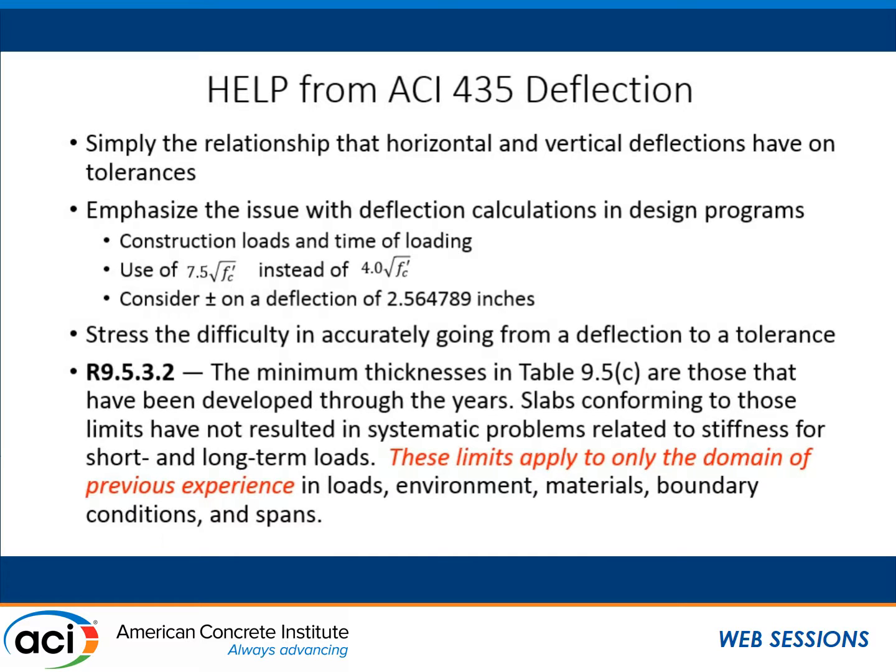We discuss it in the American Society of Concrete Contractors. We've got a little bit of an issue because most owners will pay for F-number measurement, okay, FF and FL. The testing lab does it. It's already in the testing scope, so they pay for that. The difficulty we have, and I used to own a test lab, is you don't necessarily want the test lab to be the surveyor. Sometimes they don't have the equipment, sometimes they don't have the skill, and construction surveying is totally different than land surveying. So a lot of specifications, quite frankly, are putting it on the contractor to do the construction surveying, which is okay. Some contractors are starting to do it now, recognizing the problems they've had, where they're taking their own measurements.